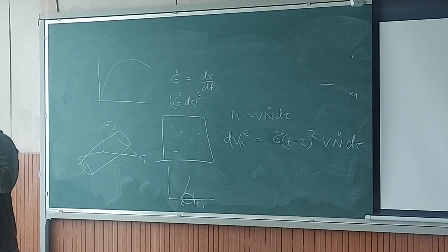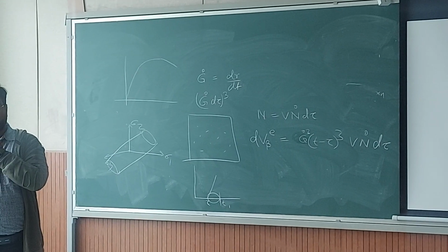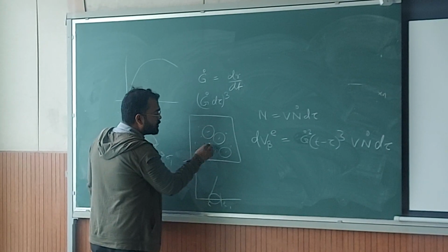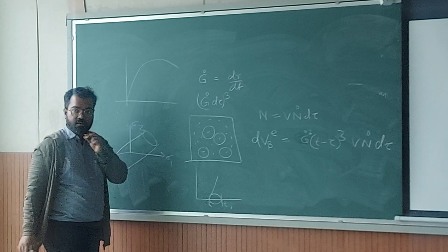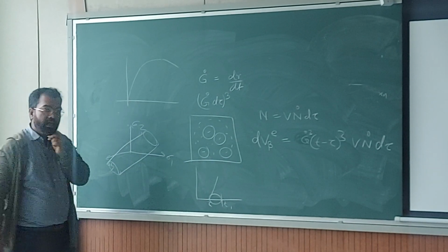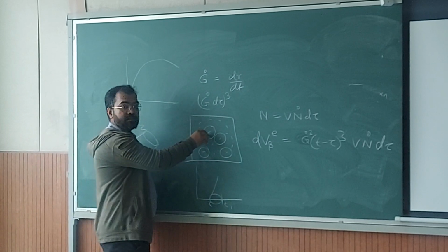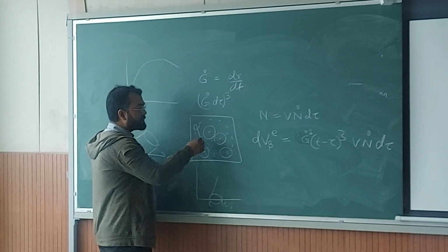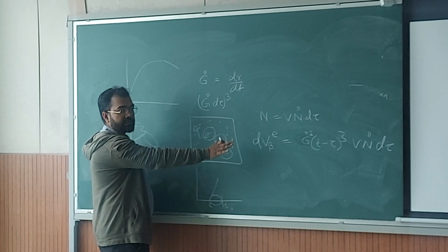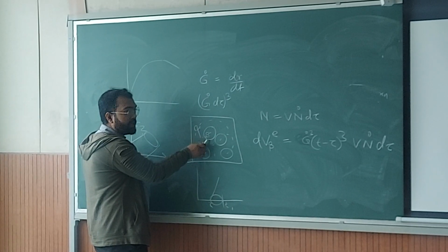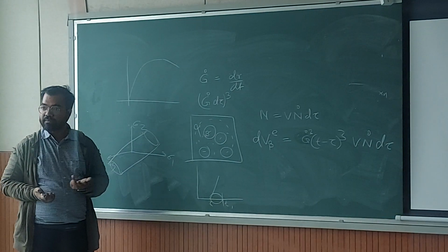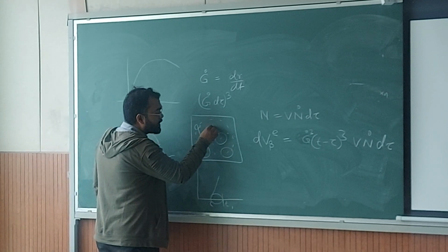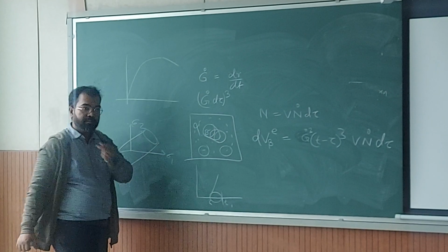and then you integrate this, and then you get a volume, and that volume is not taking care of the things. So if these are growing, new nuclei are also forming, right? And these nuclei can also form within the grown area. If the parent phase was alpha and the new phase is beta, then no equation in that is suggesting that beta cannot nucleate inside beta. That we have not taken care of, right? And then these two can also grow inside each other. That also we are not stopping.